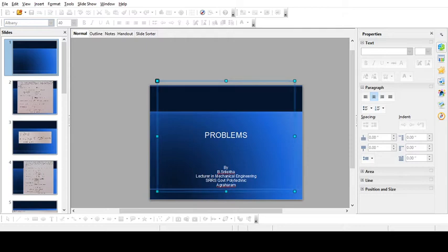Now Poisson's ratio is nothing but the ratio of lateral strain to that of longitudinal strain. So it is 1.78 into 10 to the power of minus 5 by 6 into 10 to the power of minus 5. So you will get a value of 0.2967.